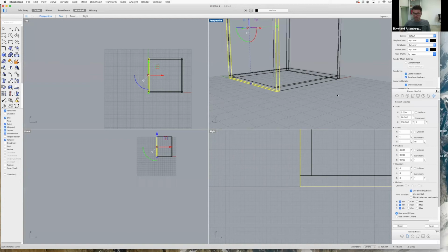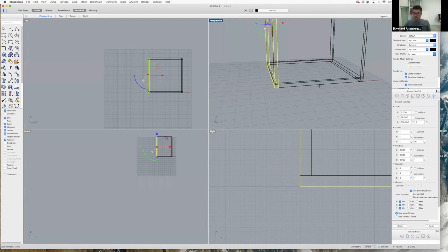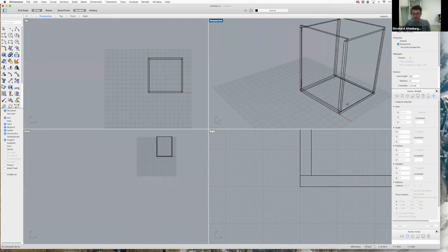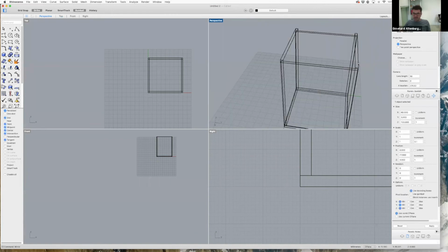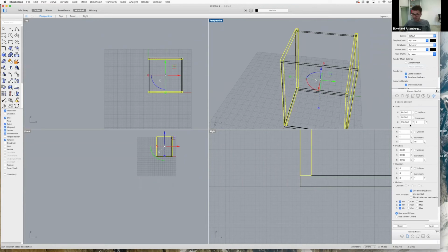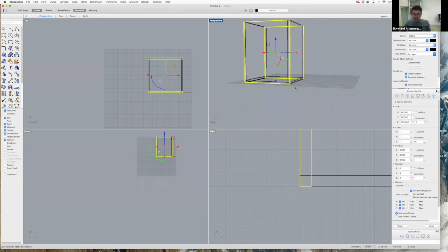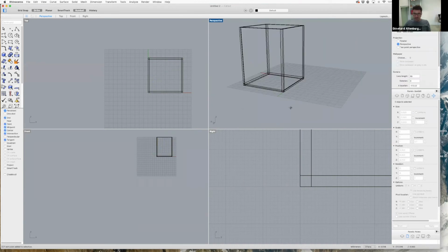So now we have these two sides. They are based on the 0 point on the ground plate. These ones still stick a little bit out. So I select those by holding the shift button, and I put them in the Z direction onto the 0 position. Apply. So you see, they're all down here now. Yeah. So this is a box.